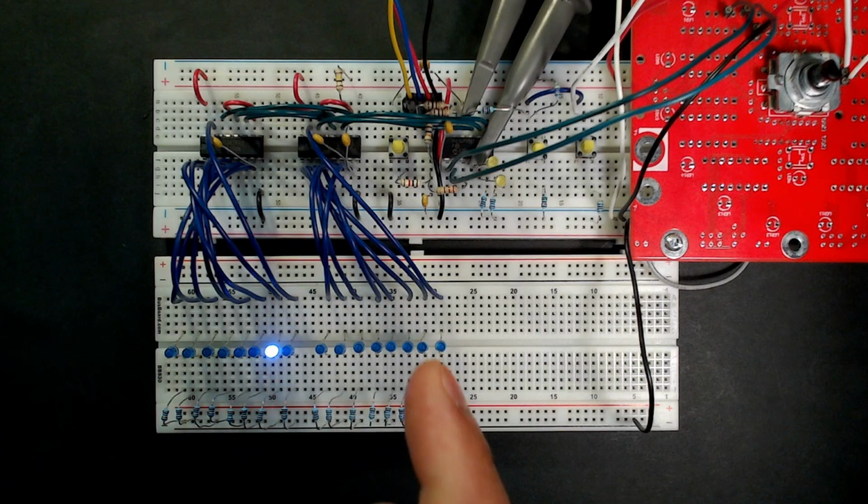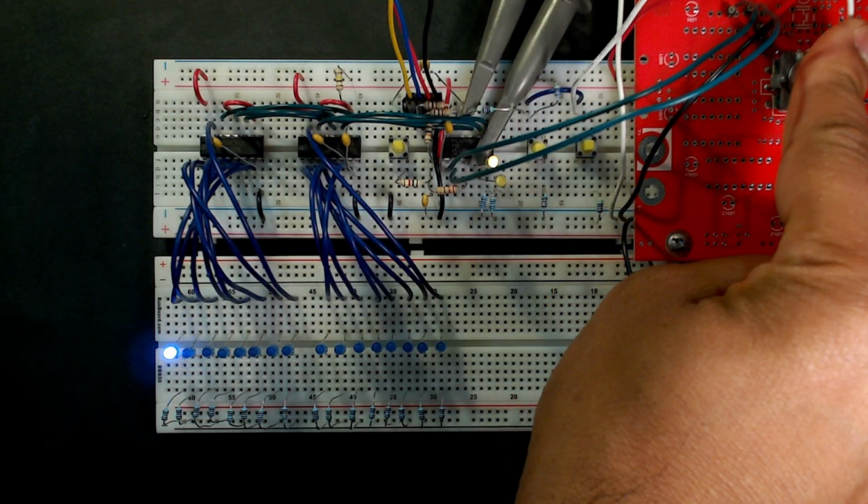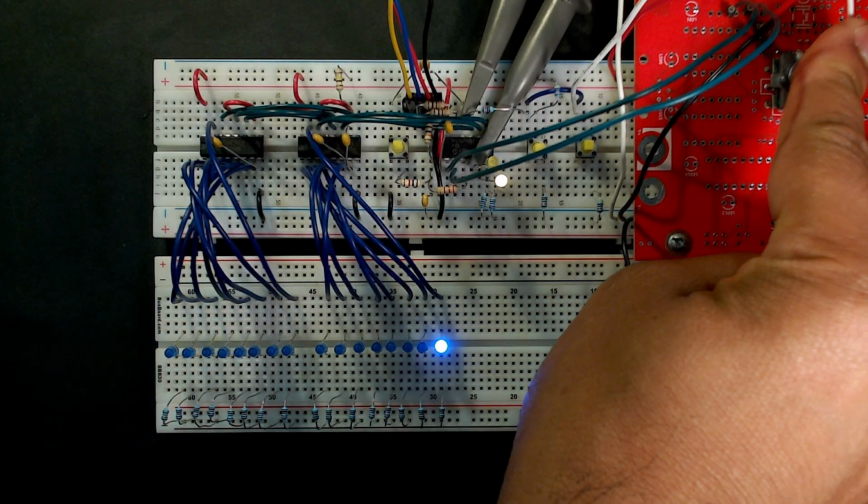And that's why I set it to 50 milliseconds, because I thought that would be an appropriate time for the transition to take place. Not the entire transition, mind you, but the transition between each intensity level. So to move from this intensity to maximum intensity, it's about 6 stages. And to go from maximum to minimum, for example, is a full 15 stages. And each of those stages should take 50 milliseconds to complete. But that also means I'm going to need 2 pointers. One to point to what the target intensity is, and another to point to what the current intensity is.